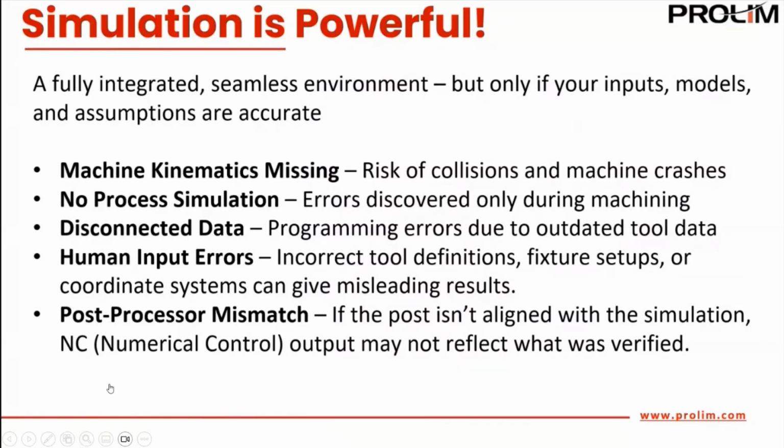Some of the things that we're seeing out there that could cause those issues are missing machine kinematics, risk of collisions and machine crashes, maybe no process simulation, so errors may be discovered only during machining. Obviously disconnected data between the design and the manufacturing side. Programming errors due to outdated tool data, human input errors, and incorrect tool definitions.